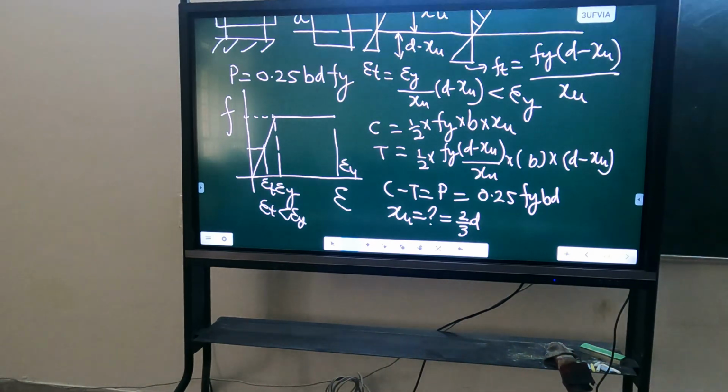How to solve this? So there has to be some axis. Now which axis will we take? One person is doing the analysis, another person is doing the design. So you have calculated moment from analysis. Now the other person is doing the design for that moment. So both should know about which axis you have calculated, because moment depends on axis. So he should know about which axis you have done the analysis, so that the design is also done about the same axis. Otherwise there will be an error.